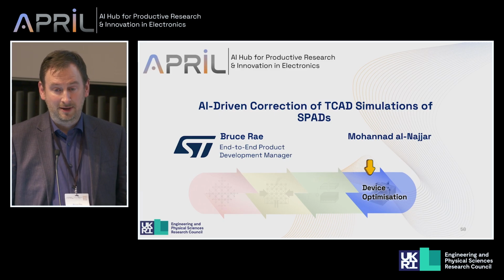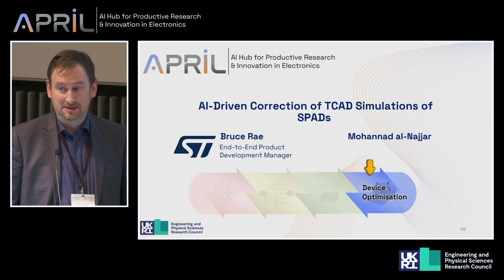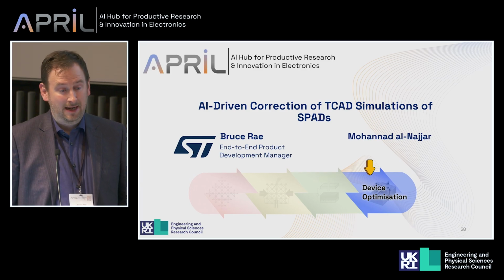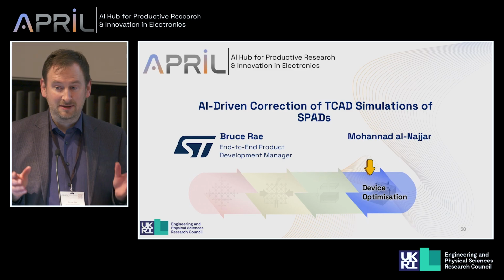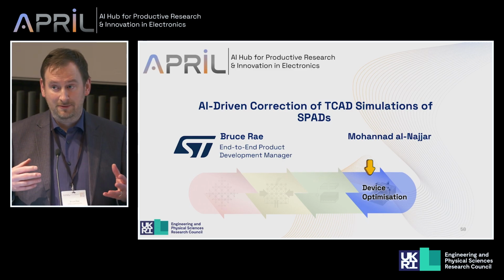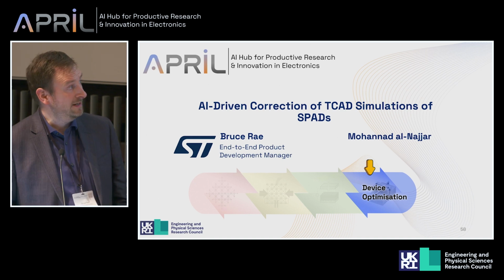These are quite unique photodiodes with unique properties, working beyond the reverse bias breakdown voltage. They are very, very sensitive to a number of parameters, both in terms of the layout and the process used to manufacture them.